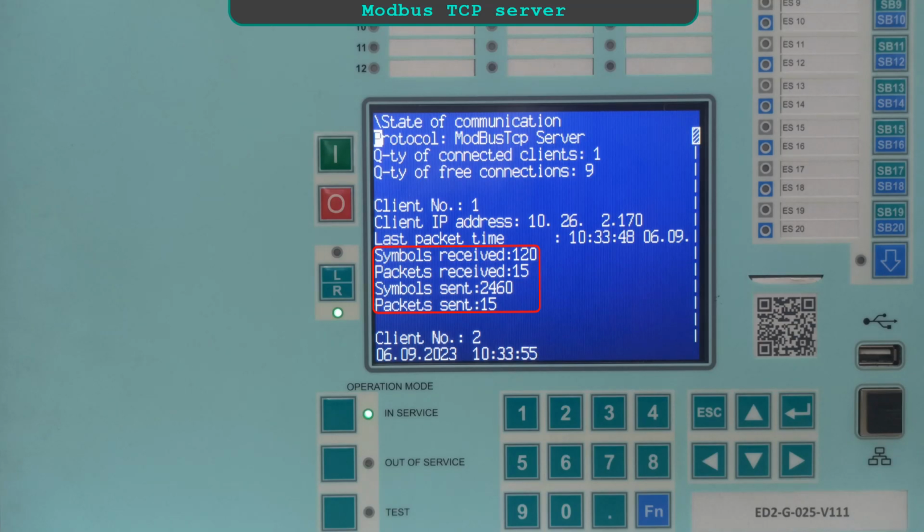If these counters values are equal to 0, it means that the connection via the Ethernet interface between the IED and the external device is not available. Another reason is the inconsistency of IP address and subnet mask of devices that have to exchange data. Make sure that devices are in the same subnet. If according to the project the devices are located in different subnets, make sure that the gateway address setting is correct. This parameter has to be the same for both devices.